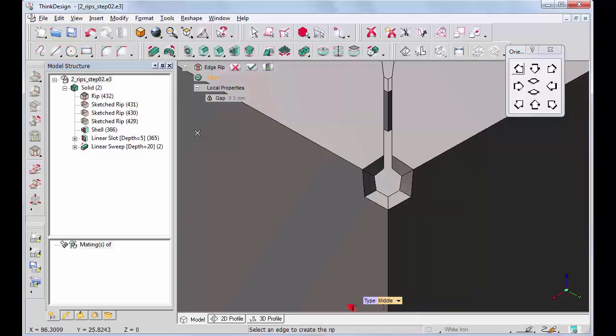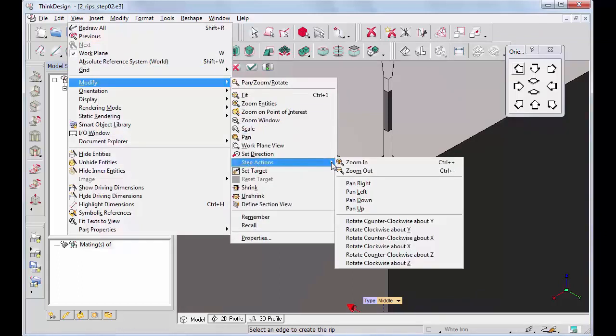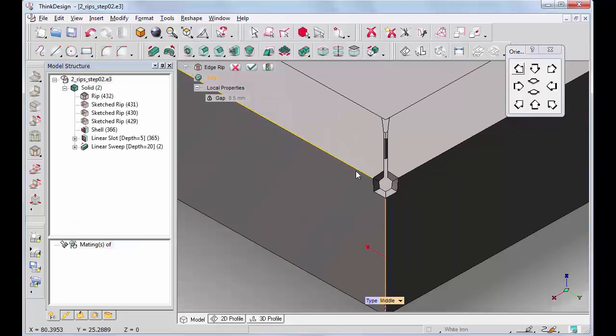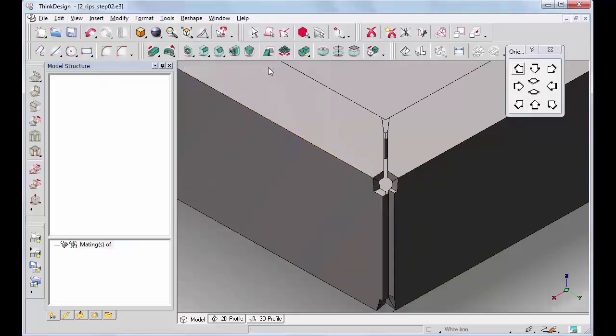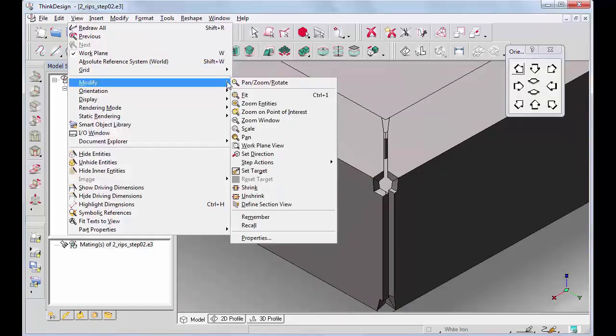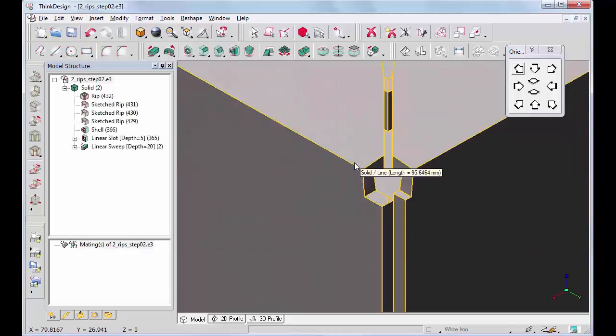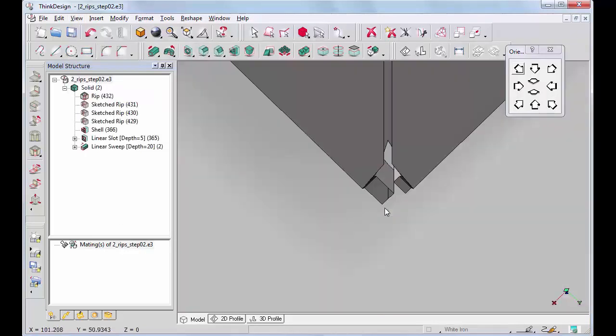In this case, the 2 adjacent parts are cut along one of the 2 possible common faces. You can choose which one by double-clicking on the arrow identifying the cut direction, and the rip will be aligned to the median axis of the selected common faces. We have properly zoomed the region in order to let you appreciate the effect on the result.